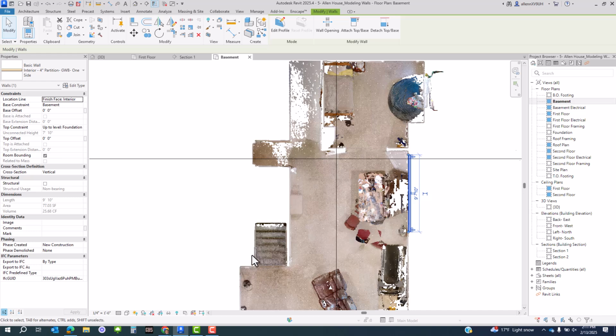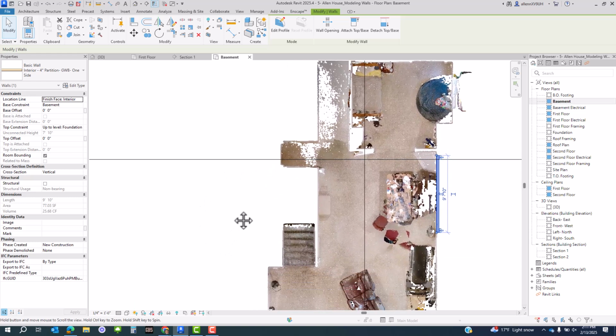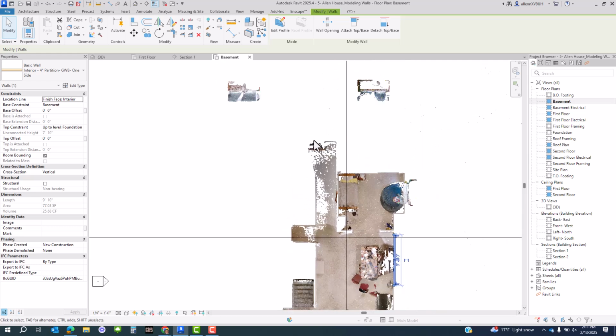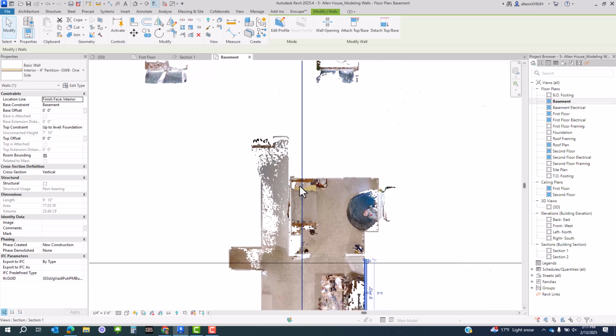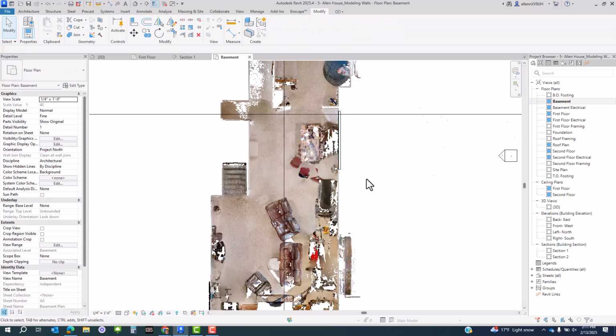you're going to have sheetrock on 2 sides where it separates the mud room, or sorry, the mechanical room. Yeah, so the wall will come here, here, here. That'll be sheetrock 2 sides, and then here, sheetrock 2 sides. All of this is sheetrock 2 sides because that's just hallway leading to other spaces. And then same with this one, and then here you'll start doing the sheetrock just on one side again, all the way back to the start.